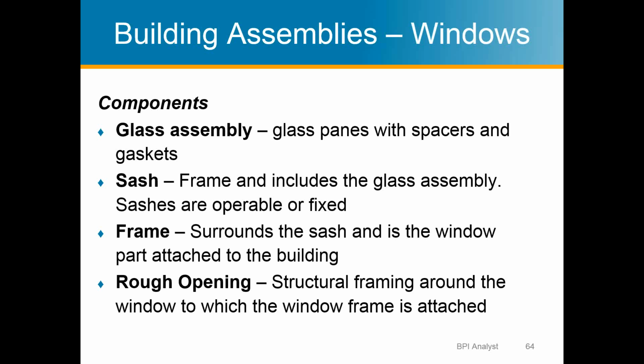And then we often talk about rough opening as well. A rough opening is what the framers gave you to put a window in. So in EnergyPro, what we should always be using is the rough opening, because that's the opening that the window is going in. It's going to be larger than the window, or the window wouldn't fit.